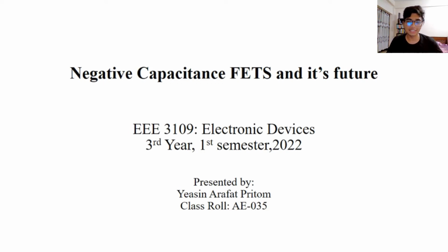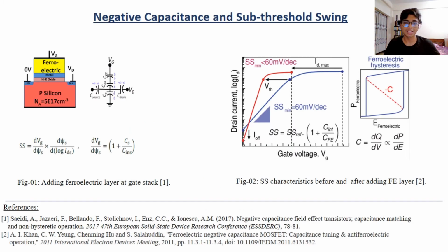I'm going to present on negative capacitance FETs. The concept of negative capacitance in FET is basically to amplify the internal potential without modification of transport phenomena. If the empirical Moore's law holds forever, then in the near future the dissipative power density in a chip will surpass the maximum heat removal limit of 1000 watt per centimeter square from an IC using conventional technology.